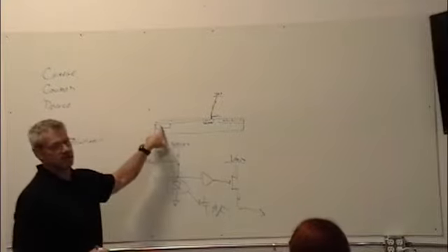And now the thing underneath is all the electronics, but the thing on top is straight diode. Well, not a diode, it's little regions of diode all over, with isolation bars in between. So if you want to do something... we know really well how to process silicon and make chips out of it and readouts, but if I want to detect an array in, I don't know, 2.1 microns, that's gallium arsenide. So now I've got to have a gallium arsenide diode array. Silicon won't detect that out there. It's outside of its band gap.